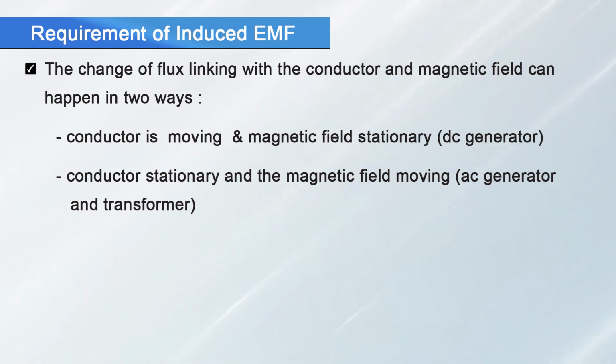Now, if we see the first requirement, the magnetic field, then flux is to be produced, and there are two principal sources of flux, that is permanent magnet and electromagnet. The basic source of flux is the permanent magnet. Here the flux cannot be controlled, as you can see. In order to have control on the machine in terms of, say, speed, flux needs to be controlled. Therefore, electromagnets are preferred, with a winding and a DC voltage source across it known as excitation. Excitation is essentially DC because it produces fixed polarity.